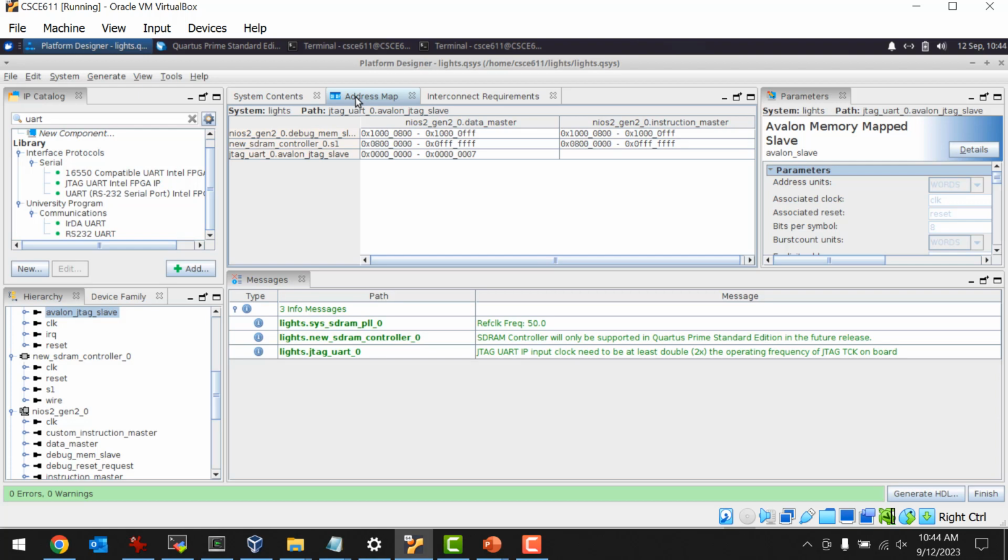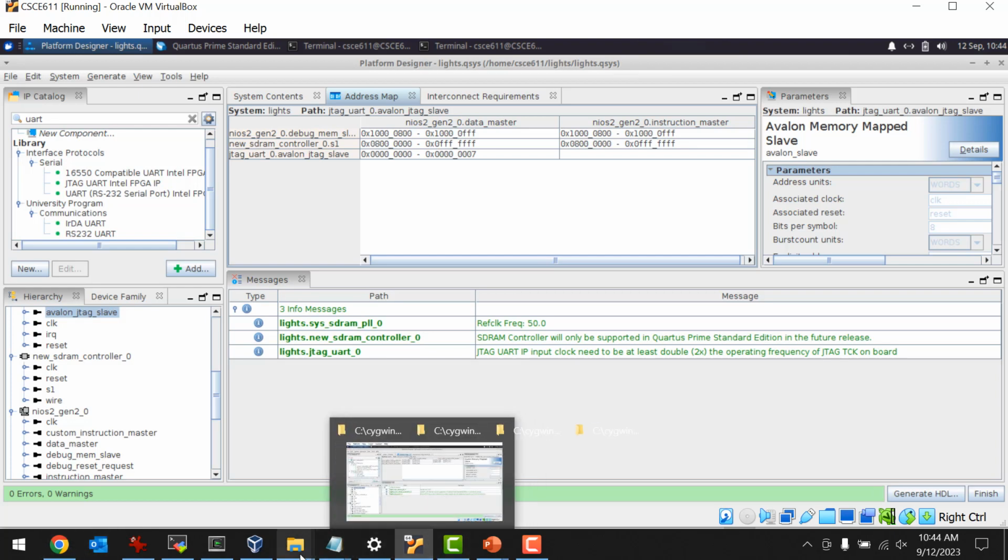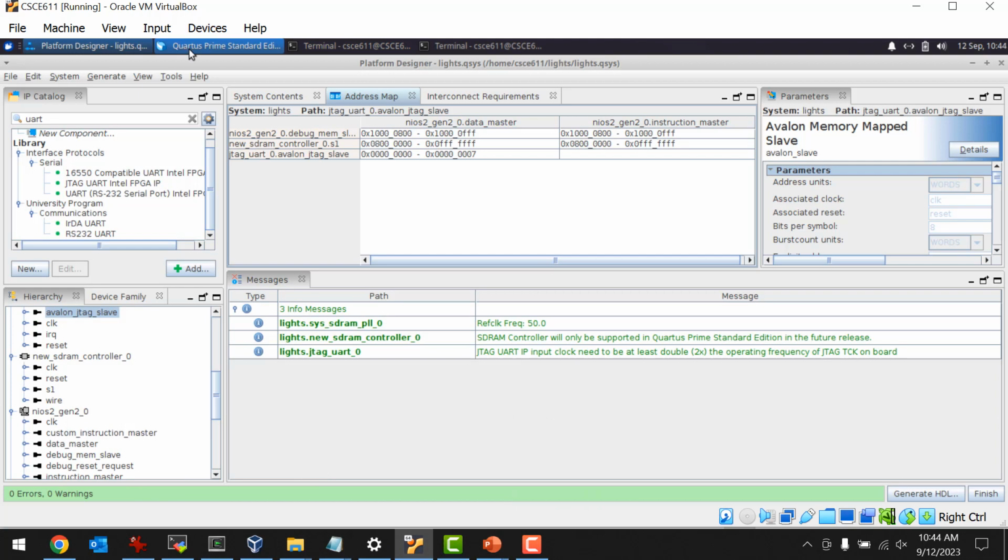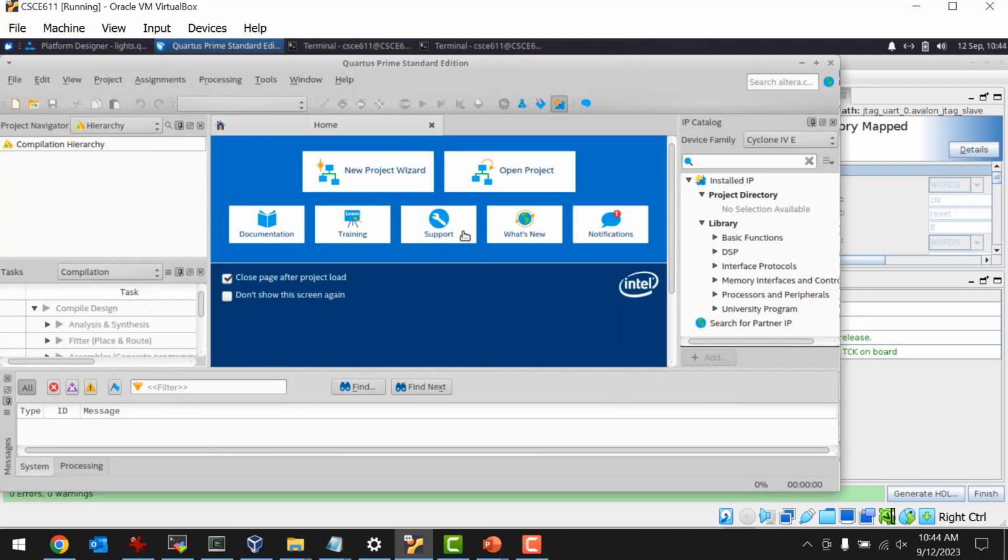And so that's the bus controller. And there's a lot of those bus controllers. So a lot of the Verilog files you'll see generated are from the bus infrastructure, but then again, the Nios processor I think has multiple Verilog files. Of course, they're encrypted because they wouldn't want you to see their precious processor design. Okay, anyway, so I think we're good to go with that, right? It looks like it generated. Okay, then once that's done, you then go back to Quartus. Sorry, we're up here. And inside Quartus, you would just bring in your lights.v, and I think you guys should be good from that point, right? Okay, any questions about that?